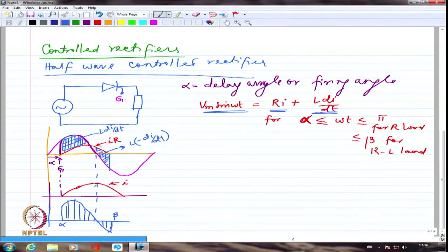So I have to essentially solve the complete differential equation, look at the regular and the particular integral, and then I should be able to say at what point, that is the initial condition, will be I of alpha equal to 0. And the final condition beta can be solved for by putting in the same solution I of beta equal to 0 and solving for beta.